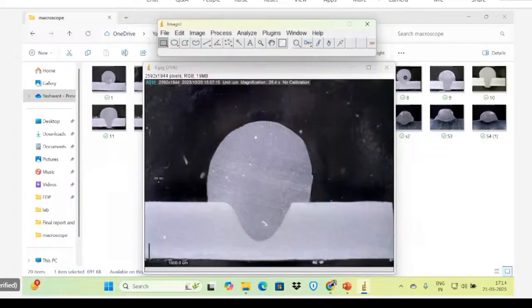That can be calculated by putting a steel ruler in the microscope and taking the image. First of all, we have to mark the scale bar on this image. It is already marked, but we have to mark it initially, because not all microscopes give calibrated images or scale bars. This one, taken at IIT Delhi, shows the scale bar, but we will mark it again.